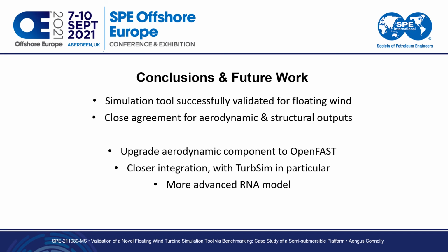Another area which I haven't really touched on in the presentation is a more advanced rotor nacelle assembly model. At the moment in Flexcom, we're using a slightly simplified approach whereby we're assuming that the rotor blades don't deflect in the wind, which is a simplification. So we don't actually model the blades explicitly using finite elements. We will do that in the next software version, and we'll model the shaft explicitly as well. So there are areas for further enhancements which we are working on and looking forward to in future developments of our modeling tool.